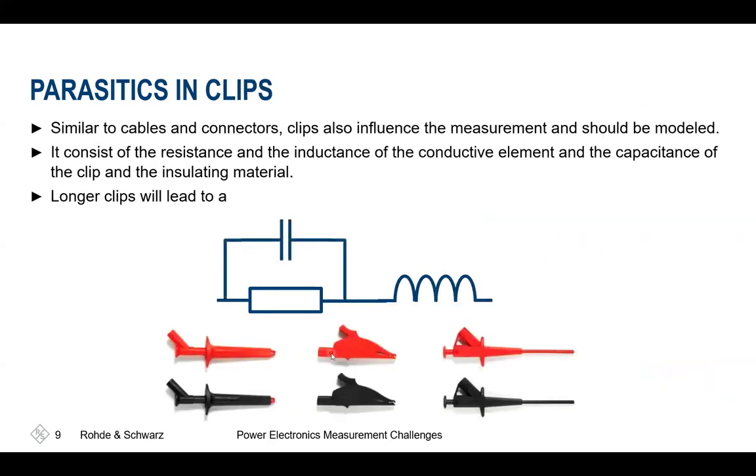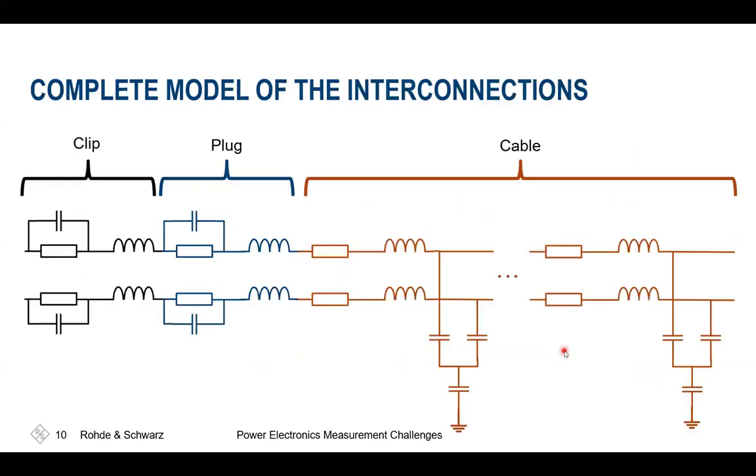And especially with these additional security connectors, there's an additional cap on there. Also, the parasitics are influenced by the clips. So if we're using the crocodile pincers or other styles of these pincer clips, which can draw a higher current than the smaller ones, all of these have different geometries, different lengths, and thus a huge and significant influence on your achieved measurement result.